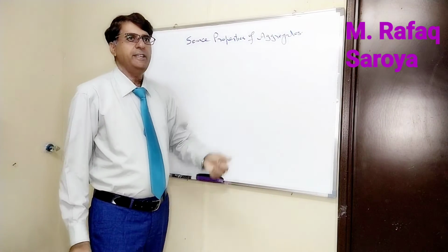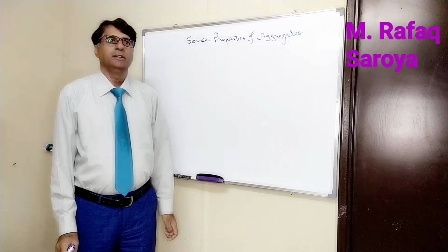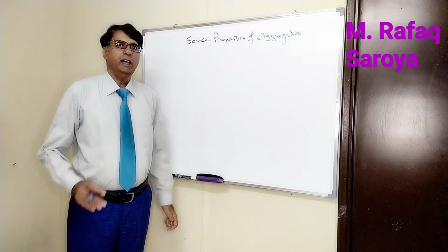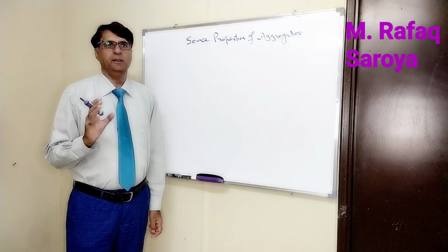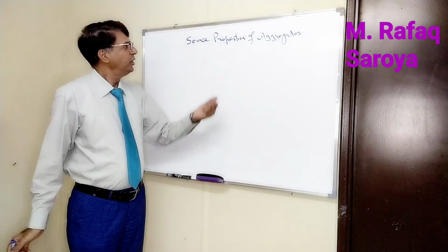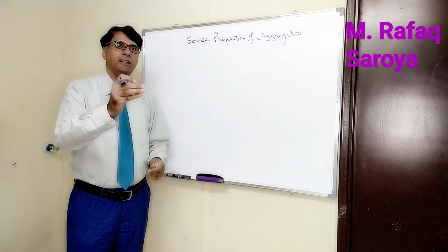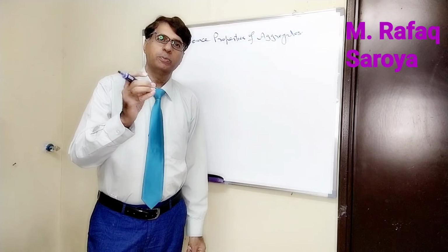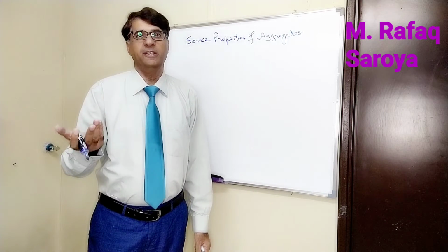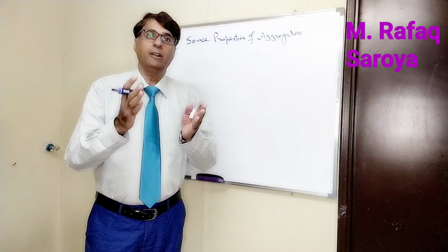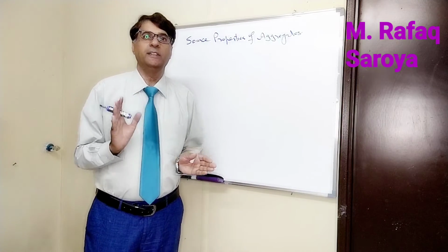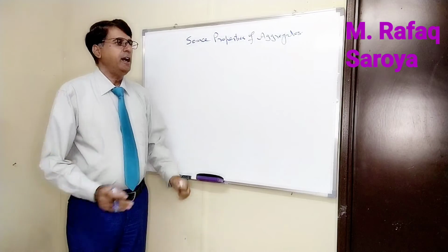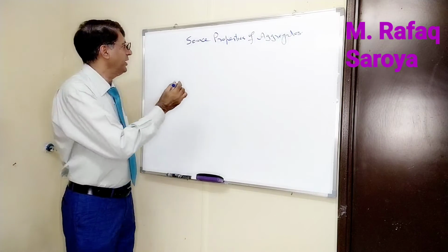This is the second group of the properties known as the source properties of aggregate. I will not go too much in detail into this one because it is very easy. Now the source property means whatever your local sources of the aggregate are available, they are also supposed to be certified by certain agency that they are quite compatible and can be used for the development of the Superpave mix design.